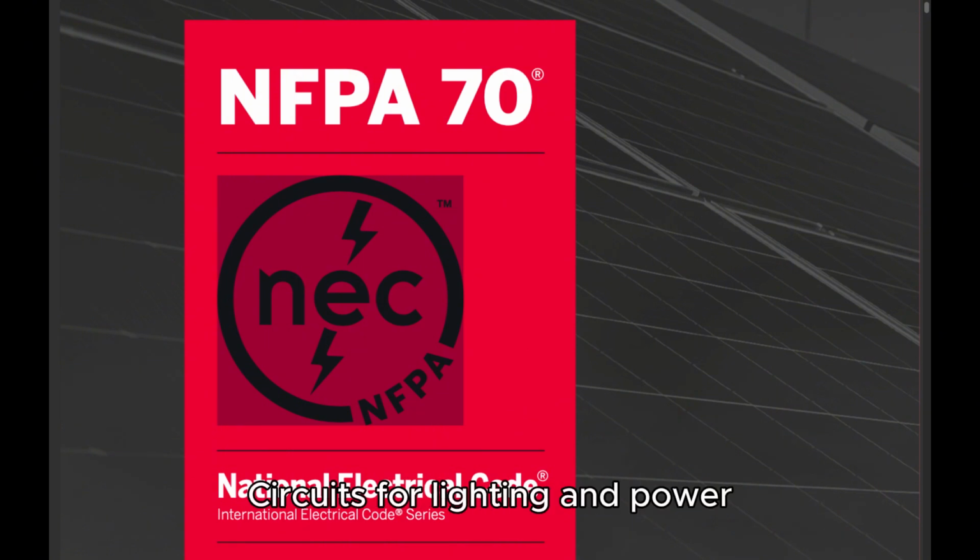110.19 Light and power from railway conductors. Circuits for lighting and power shall not be connected to any system that contains trolley wires with a ground return. Exception: such circuit connections shall be permitted in car houses, power houses, or passenger and freight stations operated in connection with electric railways. End of Article 110, Requirements for Electrical Installations, Part 1.